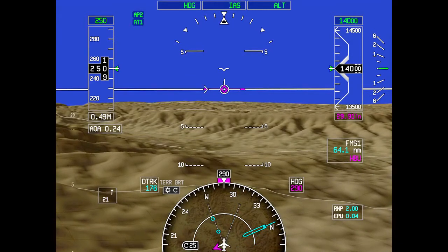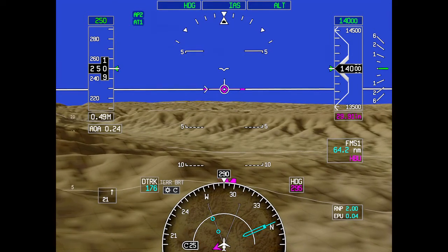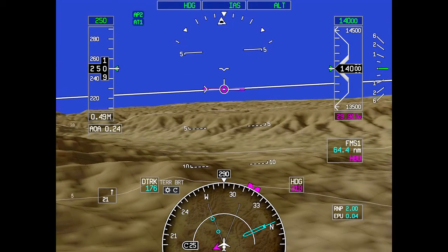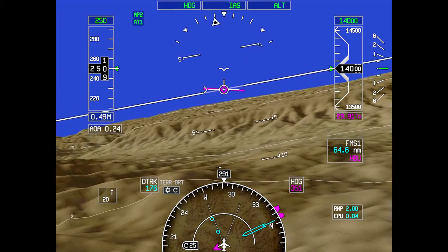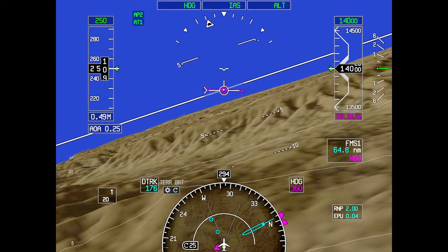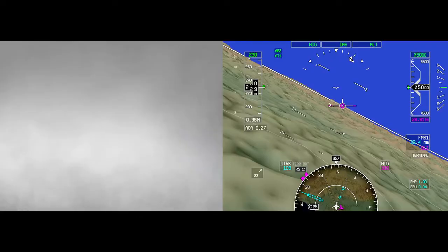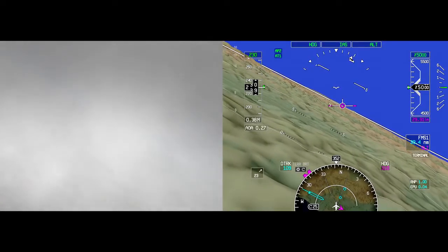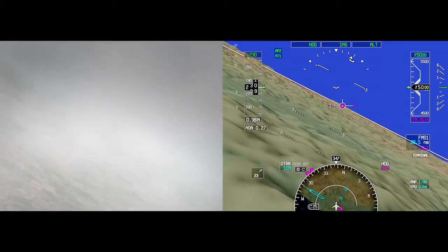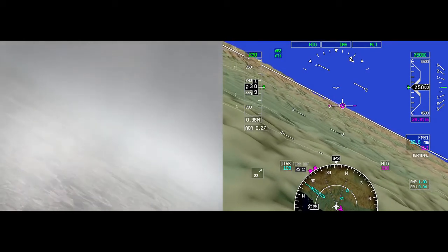This is done by using existing aircraft terrain databases from the Enhanced Ground Proximity Warning System, or EGPWS, combined with position data from the aircraft navigation sensors. This data is oriented in real time with aircraft attitude and altitude.